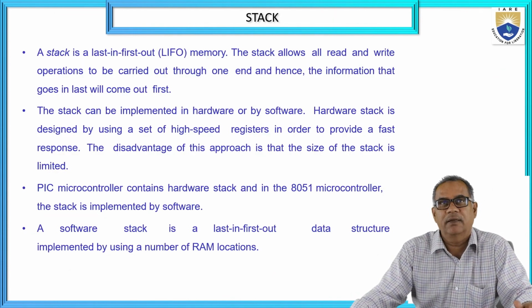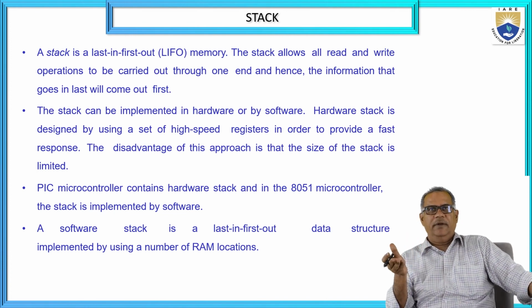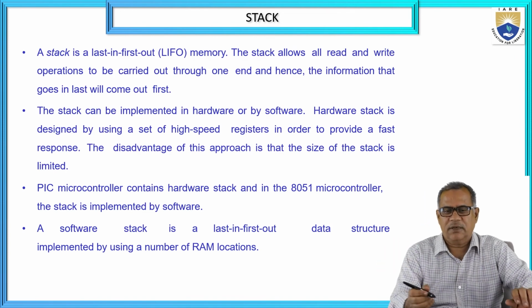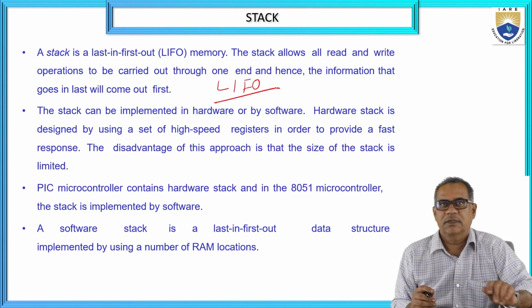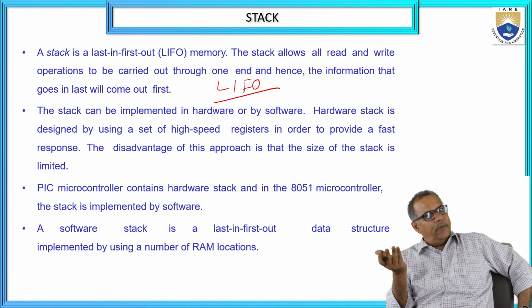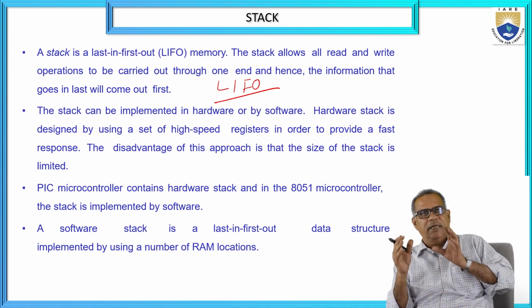So what is the stack? The stack is a last in, first out memory. So you can use the stack for read and write operations, and the information that goes in last will come out first. So this is called LIFO, last in, first out. The stack can be implemented by hardware or software. A hardware stack is designed using a set of high-speed registers so that you can have a fast response, but the disadvantage is that the size of the stack is limited.